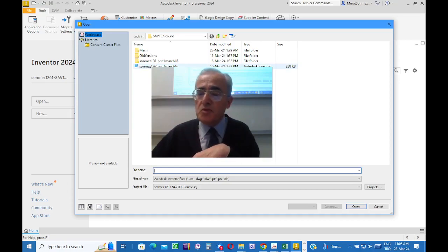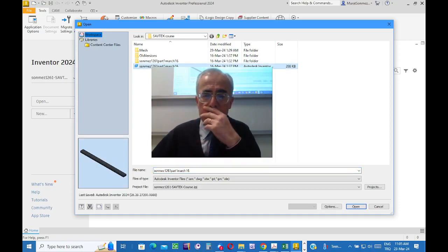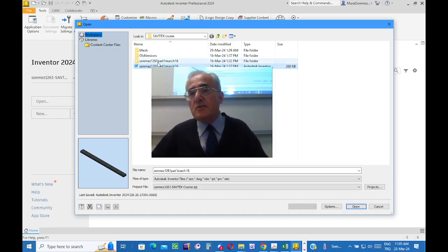This is the solid model file. The other folder, you know, in the first session I deeply underlined that whenever we use the stress analysis tool of the software and thereafter save the file one more time, the software automatically creates such a special folder.